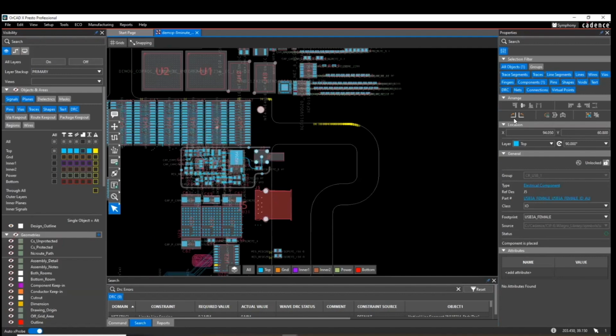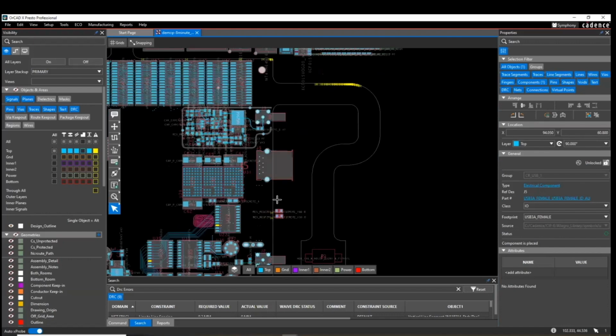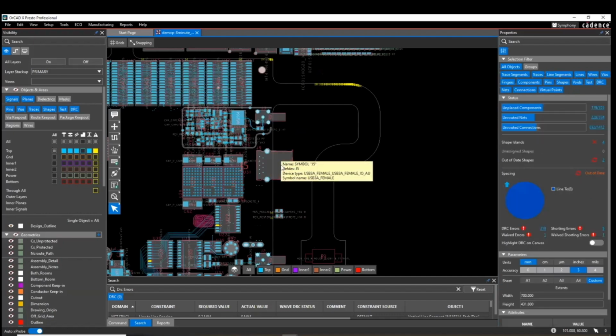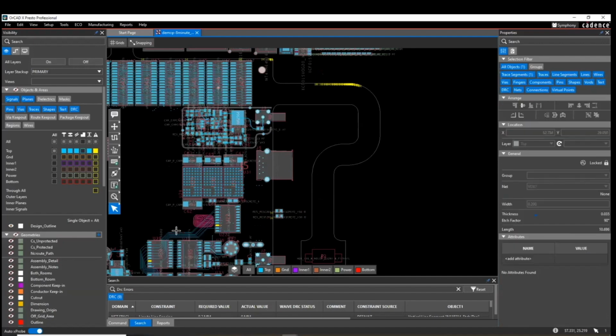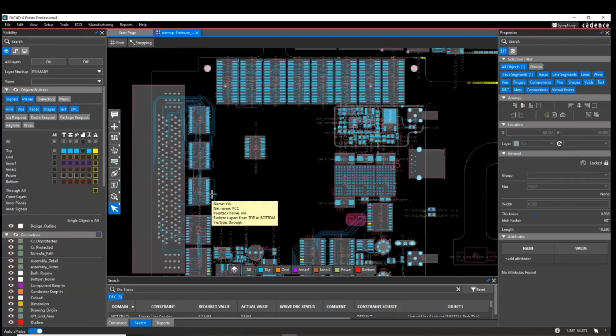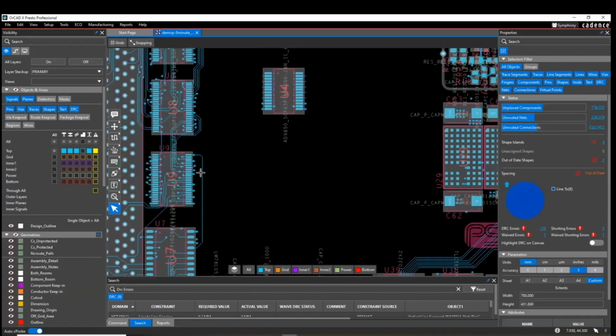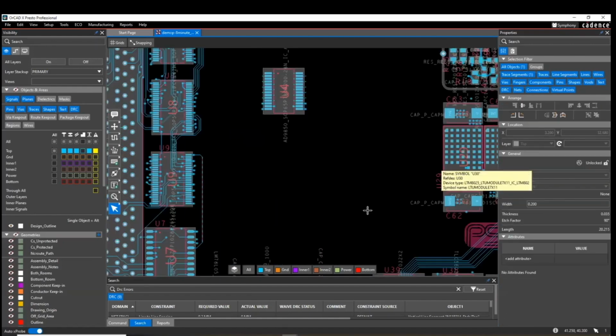And then notice that you also have the ability to manipulate selected objects from the canvas. So for example, if you were to select multiple components, you then have your ability to arrange them, mirror them, align them. So it's not only a selection option, it's the ability to manipulate options. If you were to select a trace segment or an unlocked trace, you can unlock the trace and manipulate its location in the design. For example, this net here would allow you to manipulate its properties.